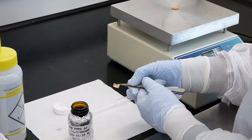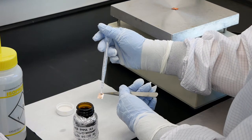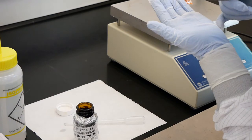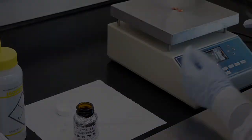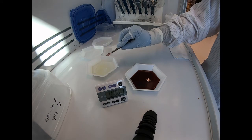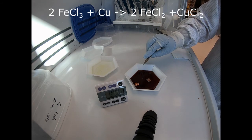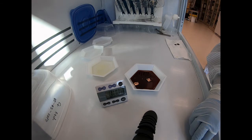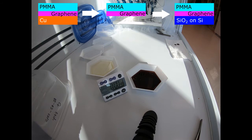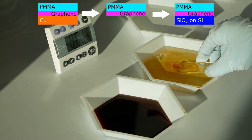To move the graphene from the copper to the silicon substrate, we use a polymer support. Polymethyl methacrylate, PMMA, is drop cast onto the copper substrate and baked on a hot plate to remove the excess solvent. After the PMMA is dry, we float the copper substrate on a bath of copper etchant. Copper etchant is a solution of iron chloride, which reacts with copper to form the soluble product copper chloride. After 30 minutes, the copper has completely etched away, leaving behind some graphene on PMMA. We wash the graphene in water baths to remove the iron chloride residue.